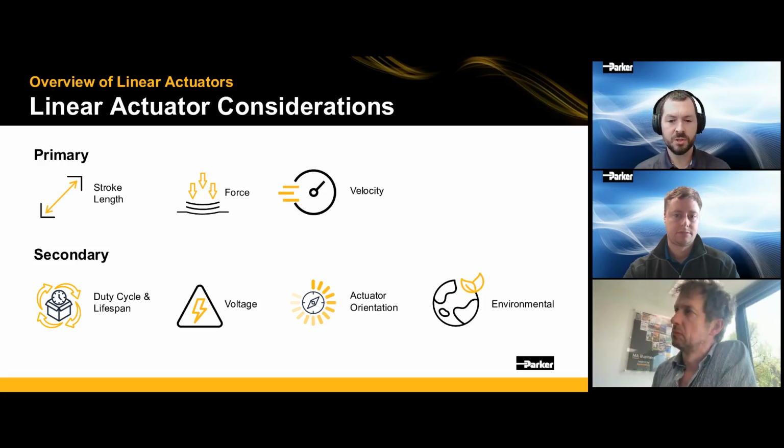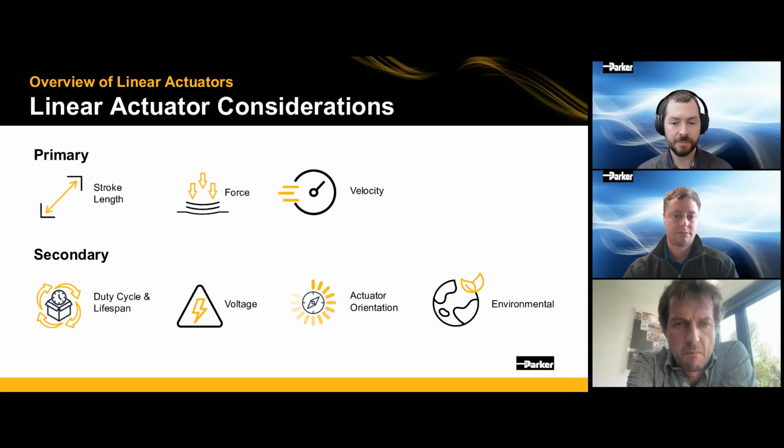You also want to make sure that you are not selecting too large of an actuator for your mechanism because you have additional mounting or envelope issues that might come up. You might have additional efficiency issues that will arise due to too large of an actuator, or you could have way too much cost to make your product competitive to the market.